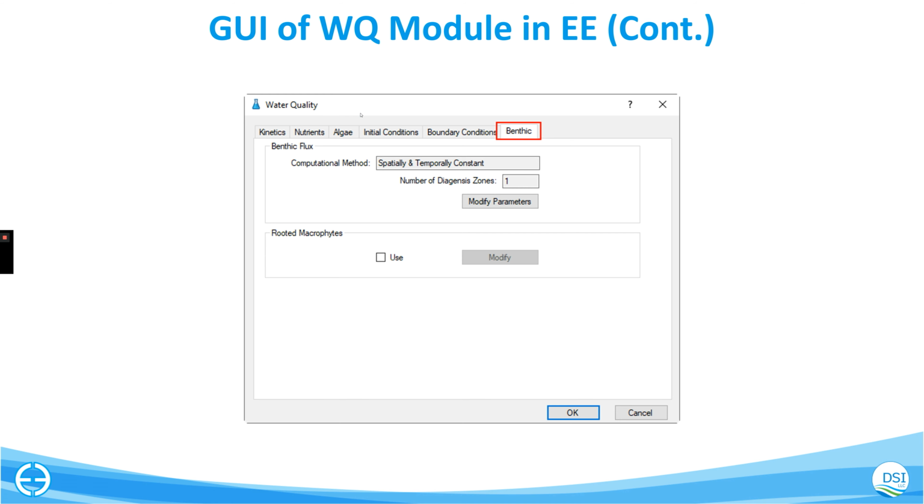However, that said, right now there is no interaction. There are two caveats I'll make here about the water quality module. The water quality module does not interact with the sediment bed; the sediment diagenesis does not interact with the sediment transport model. So if you get a big flush of bed load coming in and you've got 2 meters of bed load that came in and covered your bed from some big storm event, the water quality model is totally unaware.